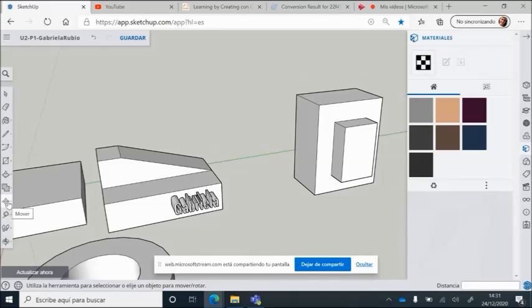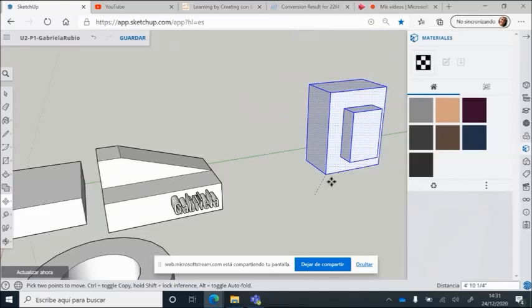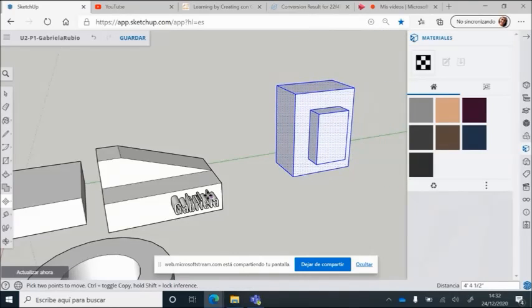Another tool that we have to understand is moving or turning or changing scale. If we select, for example, all these objects, we can, for example, move it. Of course, we can move it in any direction. It is going to, remember, suggest to us the blue, the red, and the green directions if we don't want to move the plane we're working on. And the rotation tool shows us this kind of protractor on the different planes we can work in.